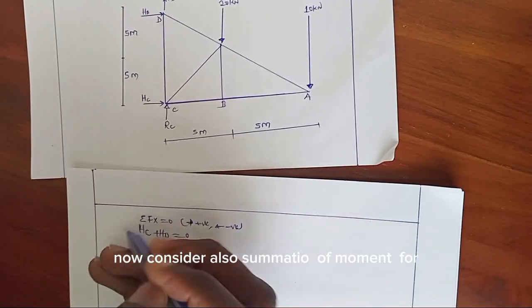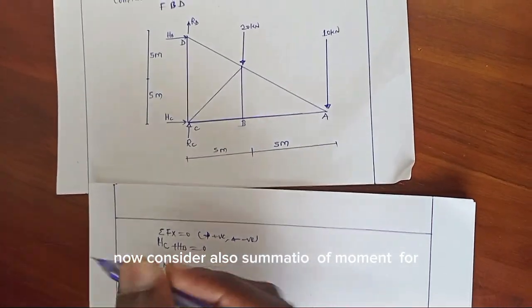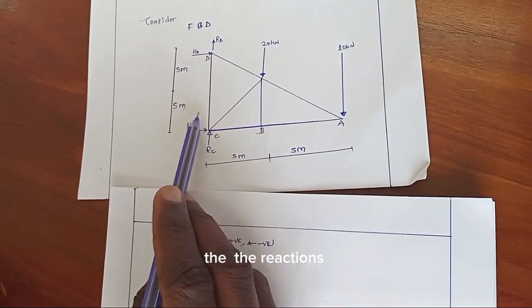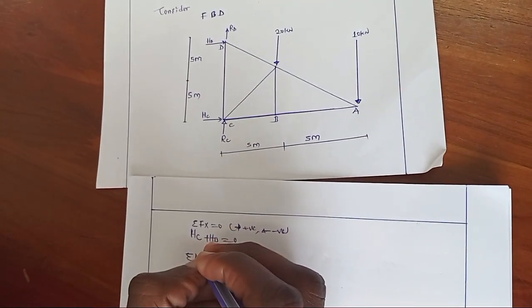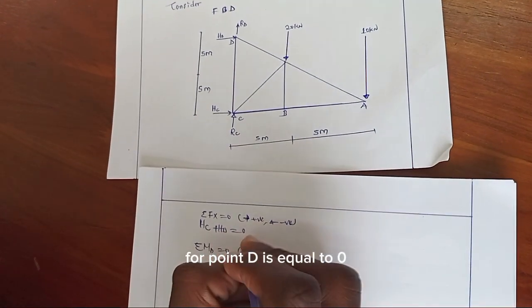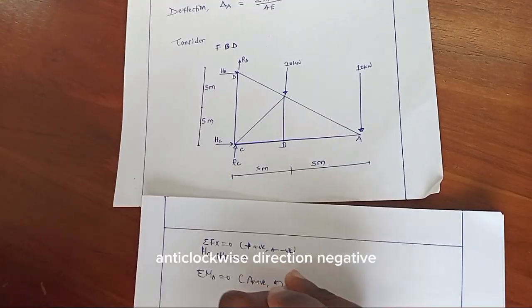Now, consider also the summation of moment at either point C or point D, so as to obtain the reactions. Now, let's consider the summation of moment at point D is equal to 0. Clockwise positive, anti-clockwise direction negative.